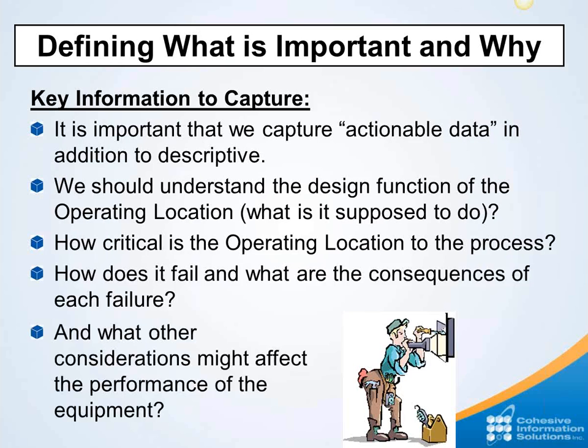So for an example, I could have a 10 horsepower motor, and I could have two of the same manufacturer model motors. One is installed to drive a pump that feeds lube oil to a bearing on a critical pump in the system, and the other might be to run a lift pump for a bathroom that's out at the intake structure. So both are the exact same pieces of equipment, but they have drastically different criticalities and failure consequences.